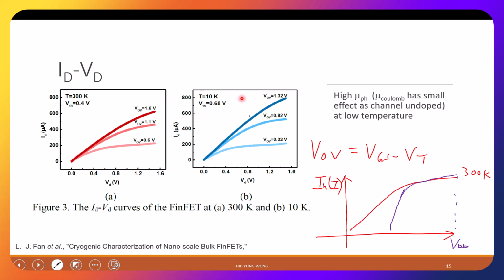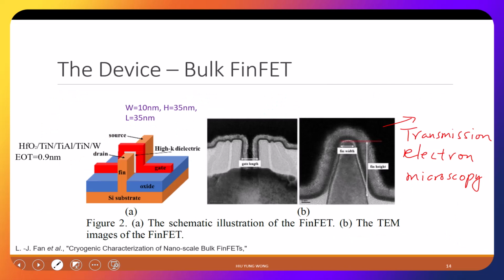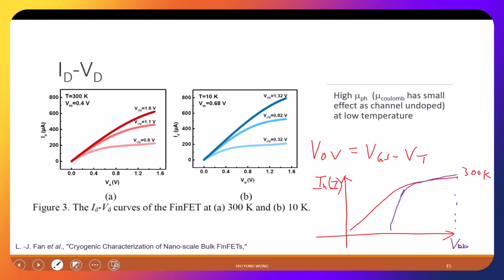But on the other hand, it does not mean that we can modify the process to get this improvement. But definitely we can reduce the voltage. I mean, we reduce the threshold voltage and reduce the VDD at the same time. Maybe the same current, but lower power consumption. No, yeah, this one can use body bias, but for SOI it will be difficult. But that's a good discussion, right? So he's saying that to do a fair comparison, maybe you really need to use overdrive, how much more you bias over the threshold voltage, okay?